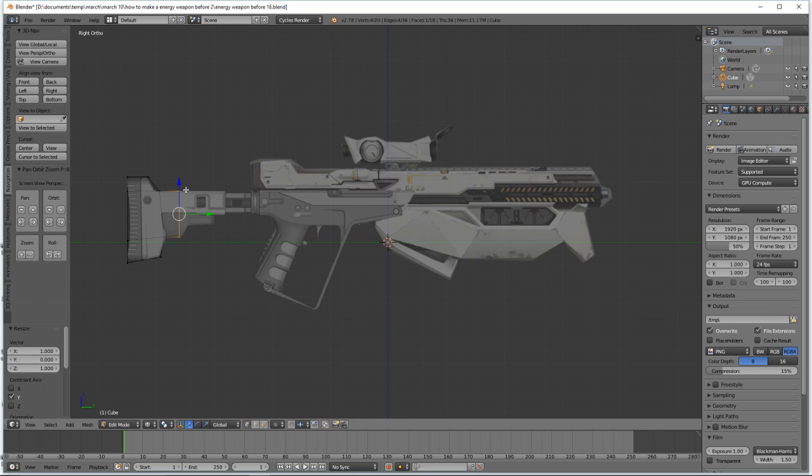Then we can see, okay, we need to go right to here, right? So what we're going to do is press E to extrude on the Y axis, go here. I'm then going to left click to lock that in. Okay, now I'm going to press A to deselect. So these vertices, I should say, these 2 that look like 1 up here are fine. This one can go up.